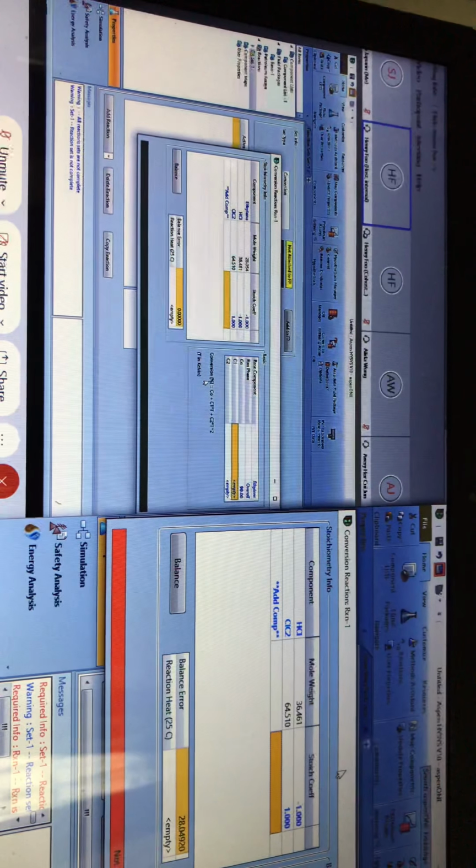Okay. Then how about C1 and C2? In HYSYS, the conversion is calculated based on the equation given below. Conversion in percentage equals C0 plus C1 times T plus C2 times T to the power of 2. So basically, this is the equation they use to calculate your conversion.